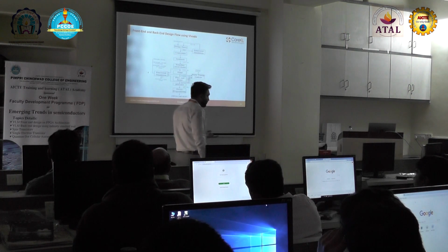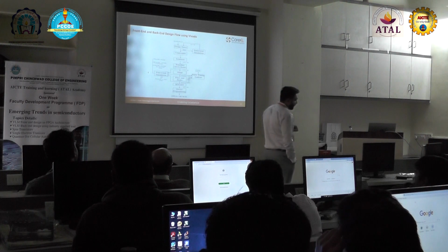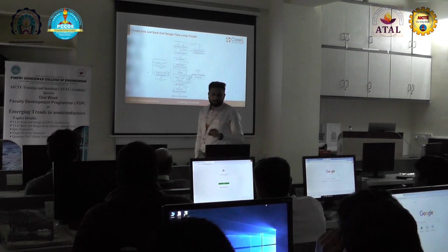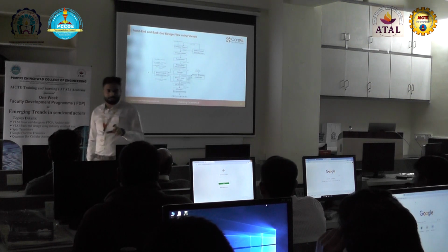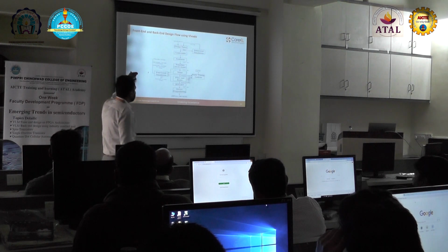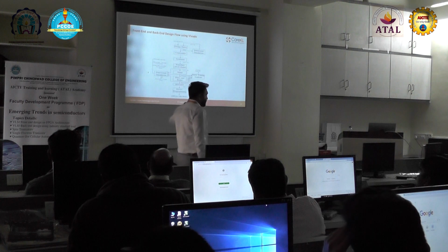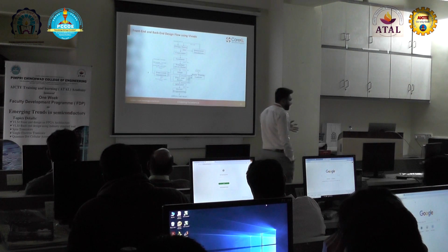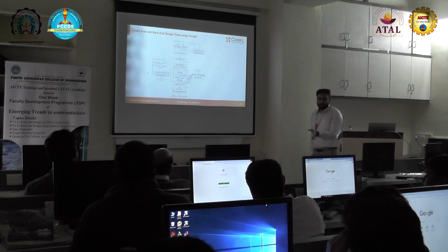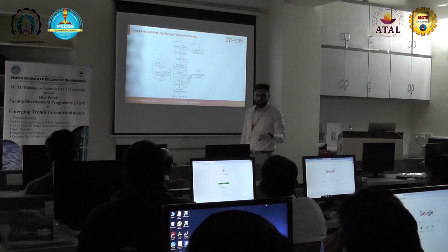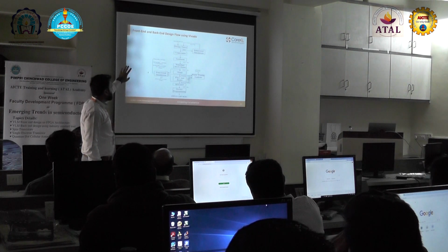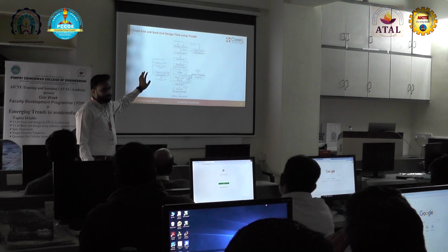After giving constraints, I have written the program for the Verilog code, meaning the design entry, and I have written the code for the constraints, meaning for the functionality, to check the functionality of the hardware. We are done with these two things. Next, I am going to the synthesis, where we check what netlist is created from the design entries, and what the input output cells, instances and entities are that the design entry has. This is done after the constraint file and the behavioral simulation.